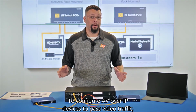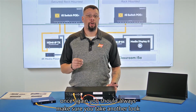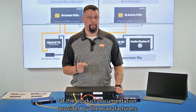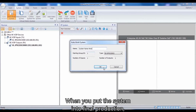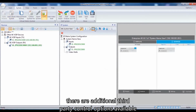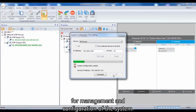To configure your AV over IP devices to pass video traffic, once again, you should always make sure you take another look at the product documentation provided by the manufacturers. For our initial setup, we will use the manufacturer's PC client software. When you put the system into final production, there are additional third-party control options available for management and configuration of the system.